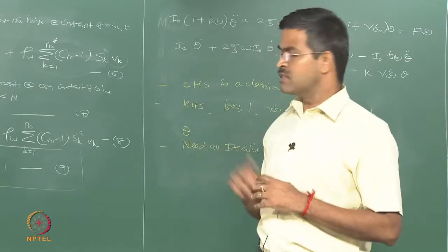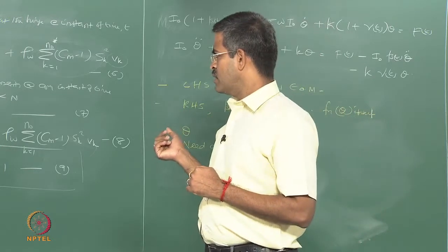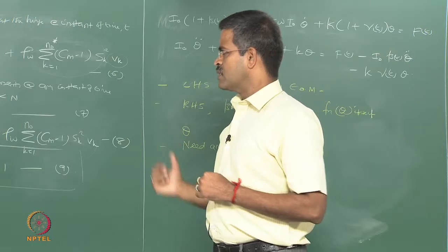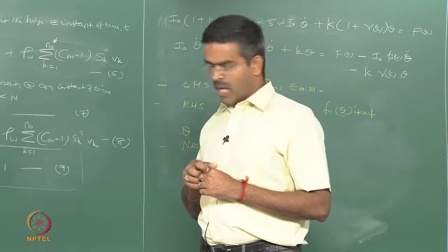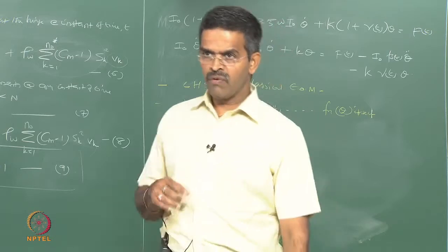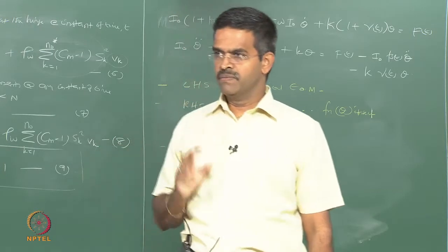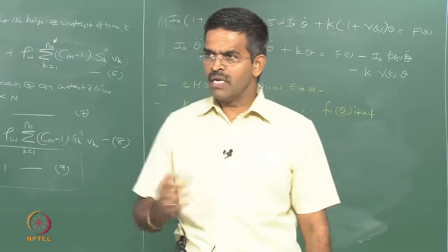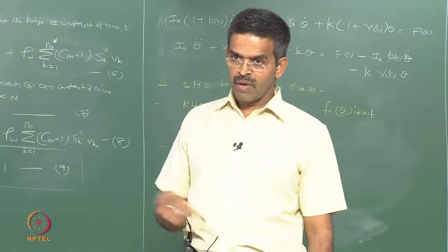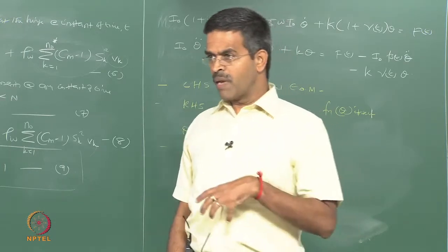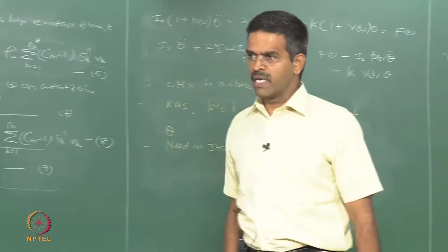Okay, that is an advantage. This does not happen in single leg. I think you will have a very interesting correlation. A single leg system will lose stability even for a small shift of center of gravity or buoyancy. Whereas if you have at least 3 legs in a given system, at least 3, not 4, 4 is redundant by one number, the CG will be playing between the 3 of them, therefore the stability is enhanced. It is very simple mechanics.